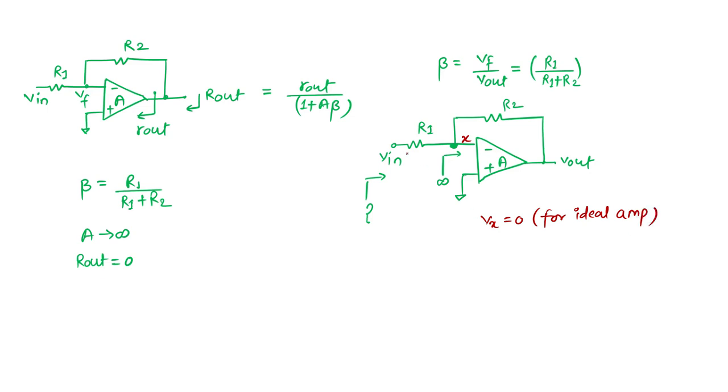If Vx is 0, then whatever the amount of the perturbation we are applying here, the current I1 flows this way, and the same current passes through this. So no current is going inside this amplifier. So what should the impedance be when we apply a test source here, instead of the input? The test current IT passes through this, and this test current is nothing but VT minus the virtual ground, which means the node X, divided by R1. So simply, VT by IT is your R1 only.